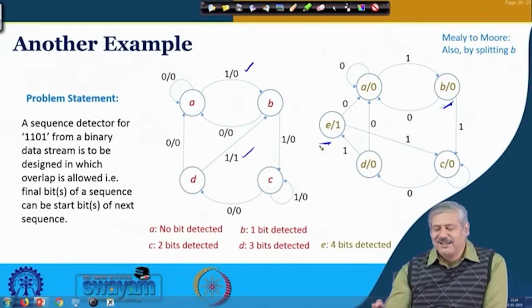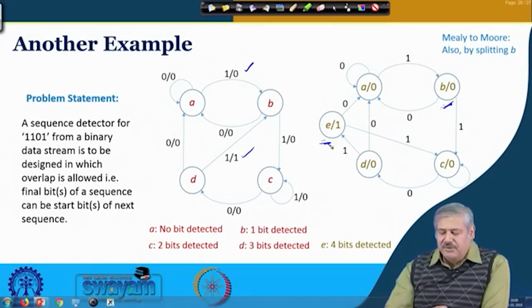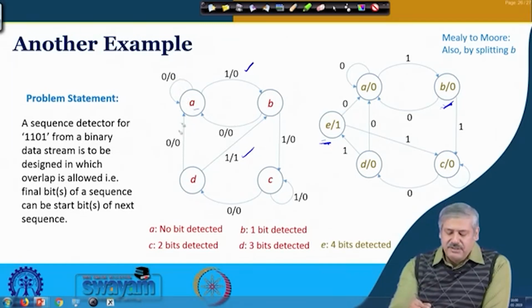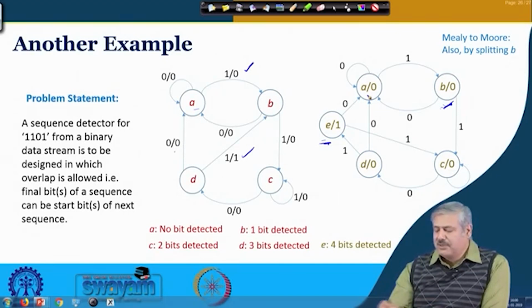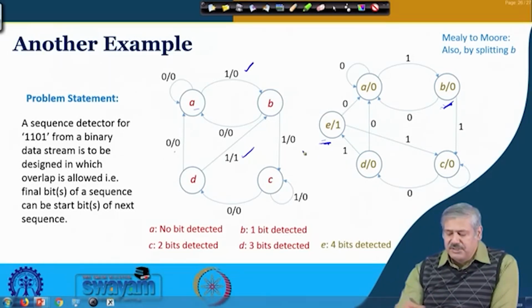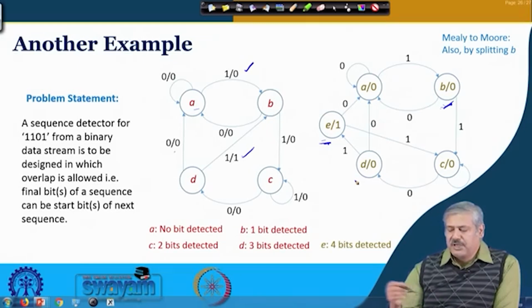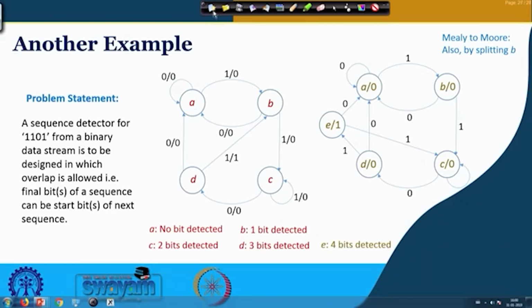You can employ that rule and see for yourself as an exercise, the way we had done for one example in the last class for 3B detection. The same thing over here, if you split, it will be B and E coming here, and the rest of the cases are fine. For example, say A, this is 0 and this is also 0. So, you can put a 0 inside. In none of the other cases is there any such issue, only for B there is the issue. You just need to follow the conversion rule and you can do it, and you can go from Moore model to Mealy model also, whenever you see that from a particular place you are having zeros and ones.